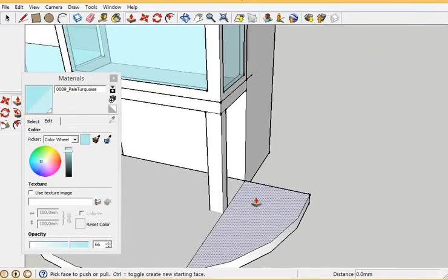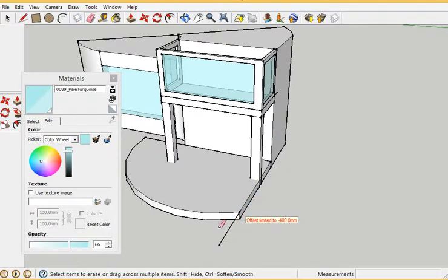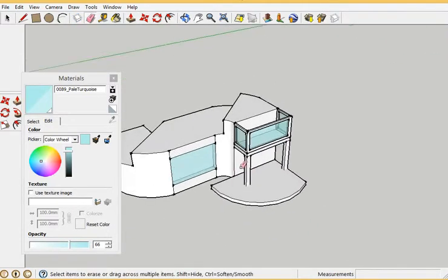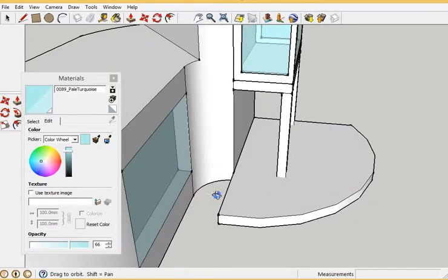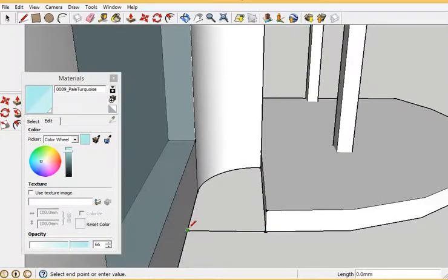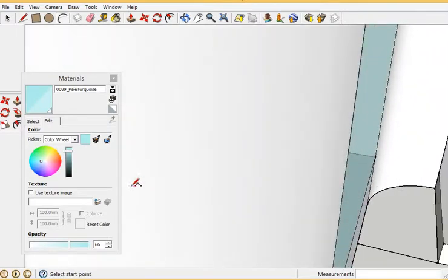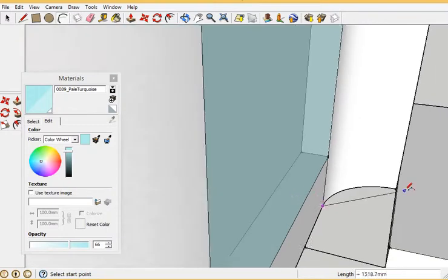If you want a little bit more control over your sketch, you can switch that on or off here. So I can edit any of my components to those original creation parameters. So if I wanted to, I could change where it glues to. Also, these ones which are grayed out, such as face camera or face the sun. So creating components is very, very useful. It's a great way to standardize objects that you use. So go ahead and start creating components for your own SketchUp projects.